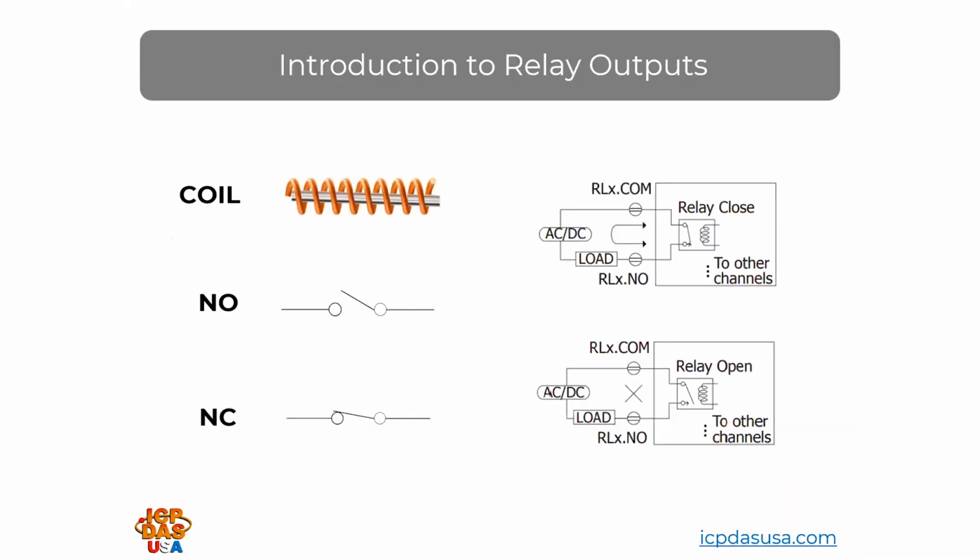Relay outputs are designed to enable, interrupt, or regulate the flow of electrical current to external equipment, facilitating control over processes and systems. An electrical signal is used to turn a relay on or off. Traditional relays use an electromagnet to control a switch. Some relays, like solid-state relays, use electronics. Relays ensure electrical isolation between two circuits.